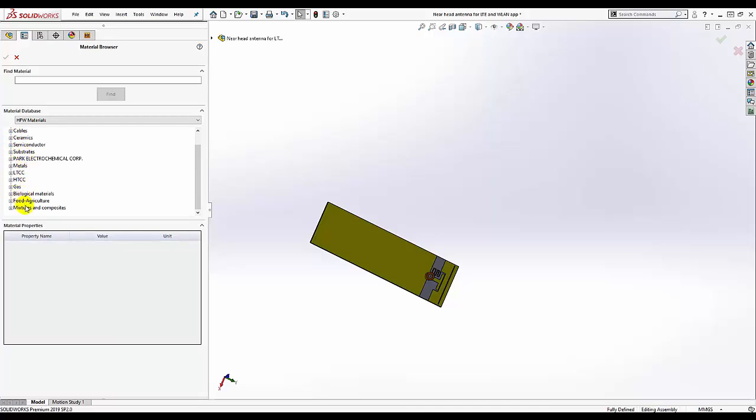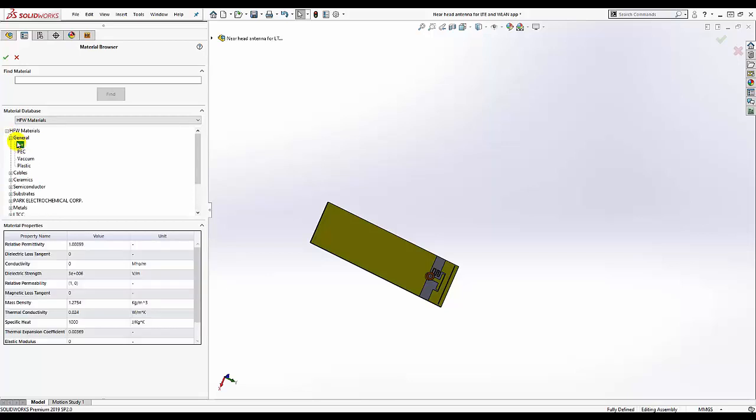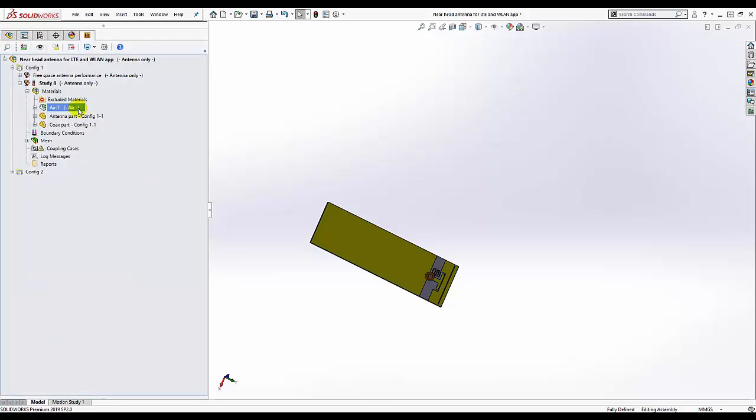We have also a new category including the biological materials, like here we have the liver, the muscle, the blood, etc. Also for food and agricultural materials, and finally for some composite and mixture materials like the coal, the granite, asphalt, etc. Once you selected your material, you have to just right click here, like here for air, and validate, and the material will be added automatically.